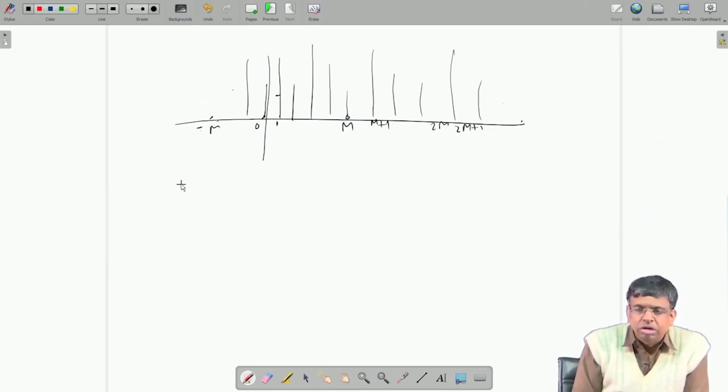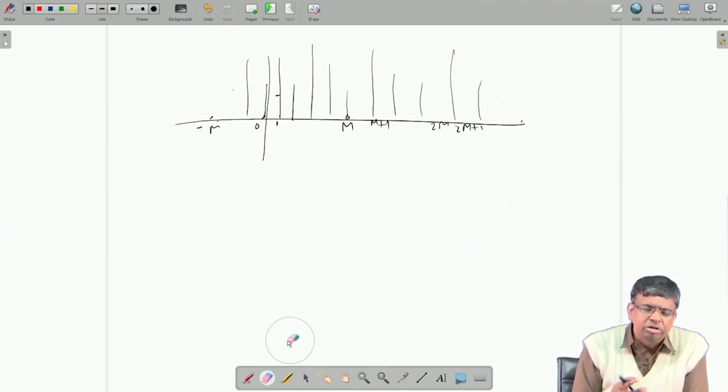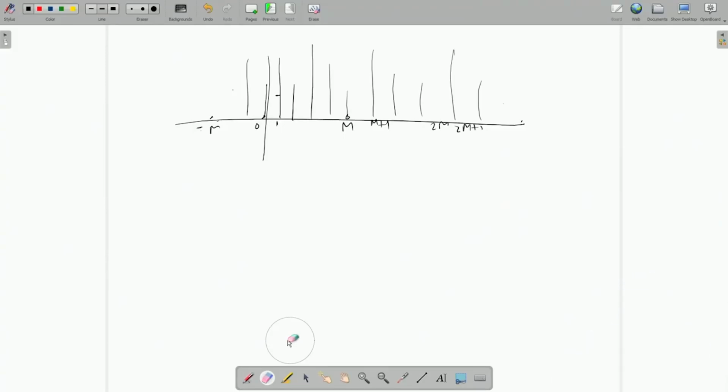Each of these polyphase components will be very handy for me in the hardware, in the unfolded realization of an FIR filter. An FIR filter has a finite length impulse response. When I try to implement it in hardware, if I do ordinary unfolding, the hardware cost will go up j times, but if I follow certain tricks which use this polyphase decomposition, it will not go up by a factor of j, but by a certain fraction, maybe j by 2, j by 3 or like that. This is a very interesting thing, it is a very involved thing, so I will not get fully into it, but at least the j equal to 2 case and j equal to 3 case we will consider.